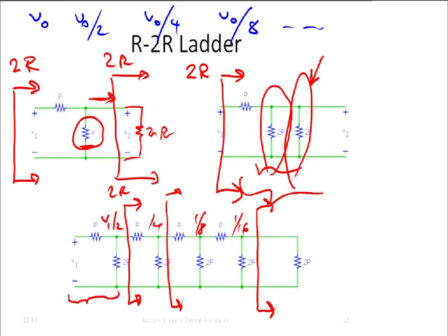Well, whether this gives an error. So if this circuit here is perfect, if the values of the resistors are exactly the way we chose, the way we indicate here, then you get absolutely no error. You can do this for as long as you want, and you always divide by 2 exactly. And our argument here showed that you could also use node voltage analysis, I wouldn't recommend it, but you'll find that you get exactly the voltage divided by 2 at